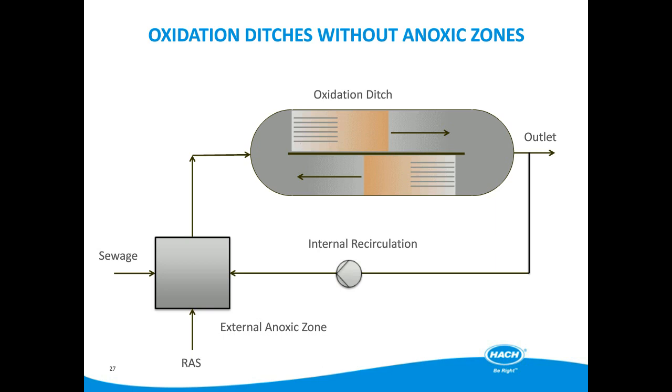Right, okay. The next one: the oxidation ditch you talked about controls the ammonia to 12 milligrams per litre against a 20 milligram per litre consent. I'm not sure whether that's correct, but it's obviously a low consent. Could the RTC actually control closer to the consent so more energy savings could be made?